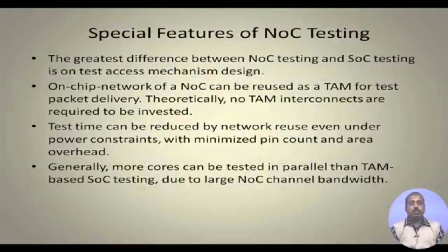So, in TAM based SOC, the problem was that we cannot test more than one core per TAM, in a partitioned TAM arrangement. So, more than one core cannot be tested simultaneously on a TAM line, and if it is a flexible TAM architecture, then for a core to be tested, all the TAM lines required by this particular core must be free. So, this type of